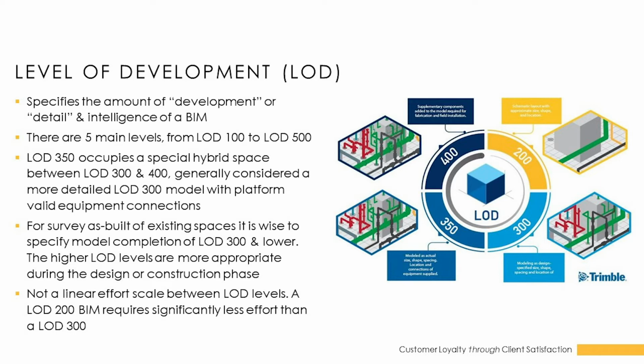There are 5 main levels of LOD from 100 to 500. There's also an LOD 350, which kind of occupies a hybrid space between 300 and 400. It's generally considered a more detailed or more developed level 300 model with valid equipment connections within your BIM software.